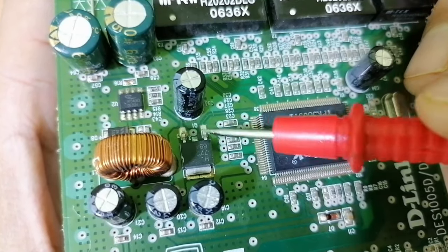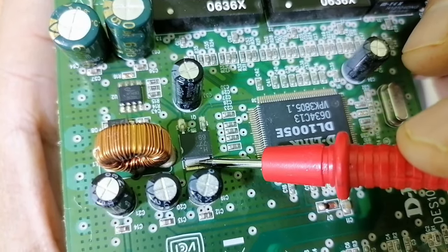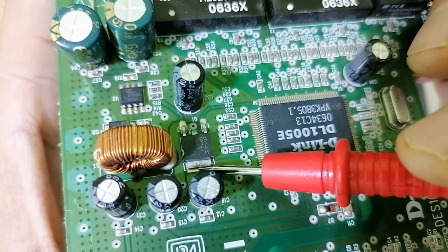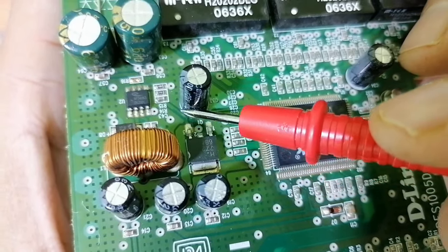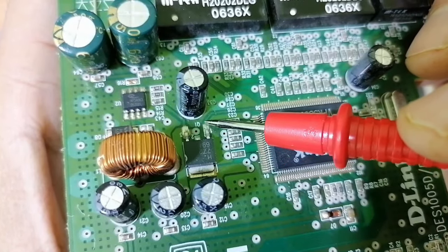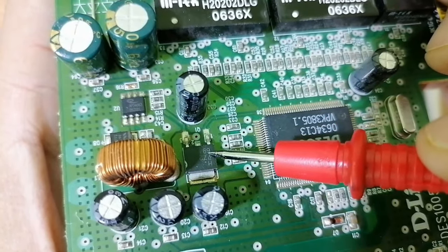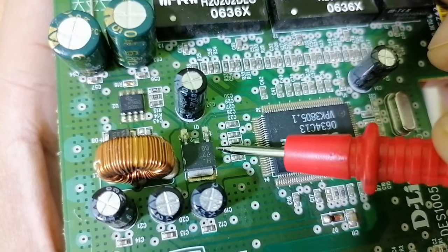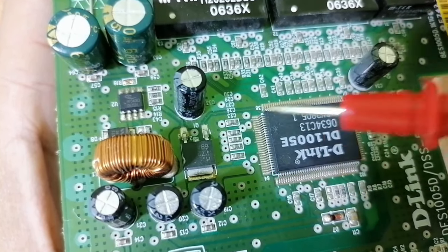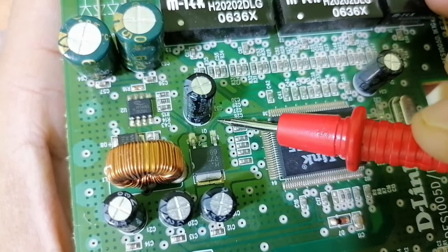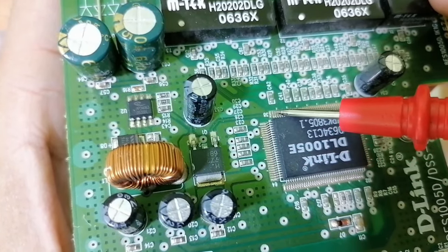You see the bolded line, and here we have the drain. So the power is passed from this terminal to drain to source, as you can see. And here we have the gate. Do you see the gate? So this MOSFET also, I can even know the control IC. So this IC controls this MOSFET, as you can see, because we have this line coming from here.